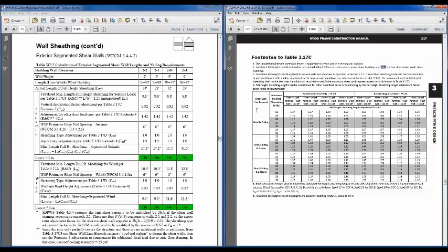Here in footnote 4, there's a big table, and I mentioned that our attic system doesn't stretch across the entire system. So I'm just going to go straight to our assumption here: a roof ceiling assembly dead load of 25 pounds per square foot. Again, you can look at that on your own. There's some engineering judgment assumed here in choosing those increased dead loads for that additional roof ceiling assembly because of the attic. But that 1.24 factor is what we're assuming as an increase.